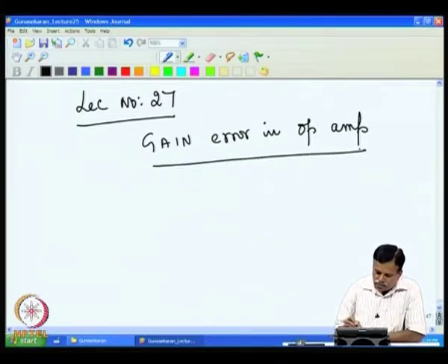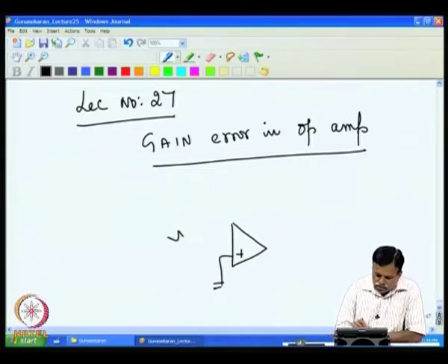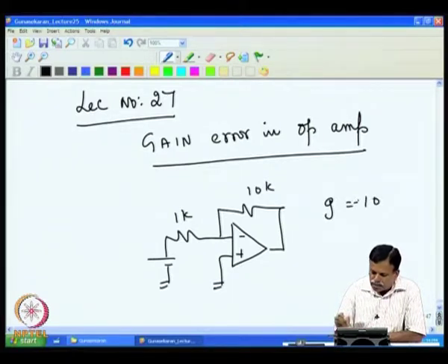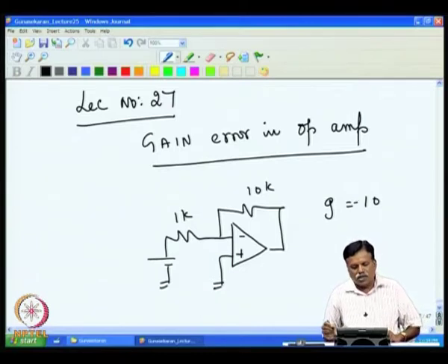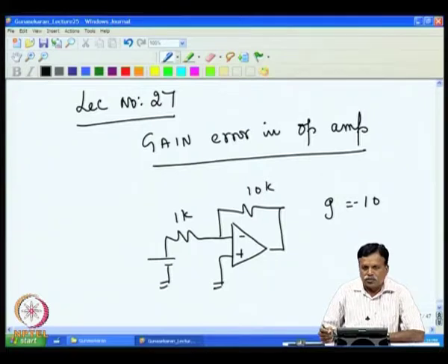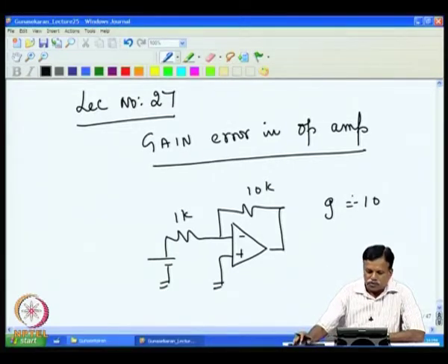Because we had seen that to operate the operational amplifier with a certain amount of gain, for example, if I want a gain of 10, we merely put two resistances with the ratio of 1:10, for example 1k and 10k, then you get a gain of basically -10. But this is only an approximation, and if we start designing the circuit with this, soon we will find that our circuit is not accurate enough, and we get into very many problems.